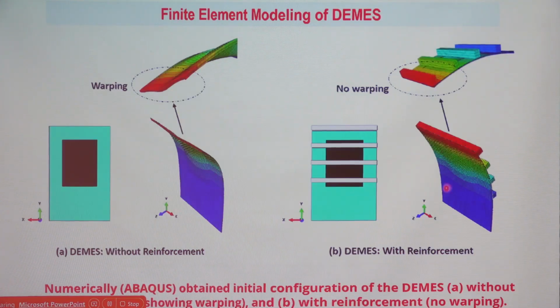So you see the number of elements that you can see. If you look at this clearly, it's very fine. So we have done the mesh convergence analysis, obtained the suitable number of elements required for this, and then implemented it in the entire required simulation. So that is clear to you. So that is one thing.